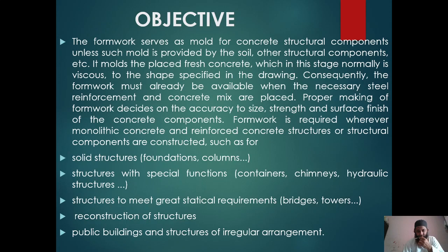But a slight difference between the shuttering, centering and the staging is: the shuttering is that mold which is used for vertical members, and centering is that mold which is used for horizontal members, such as slabs and beams. And what is staging? Staging is those members which are used to keep the molds fixed. Like we provide props, and we provide wooden bullies, so that these formwork are in a fixed state. They shouldn't move away when we pour fresh concrete. So this is a slight difference which we need to know.